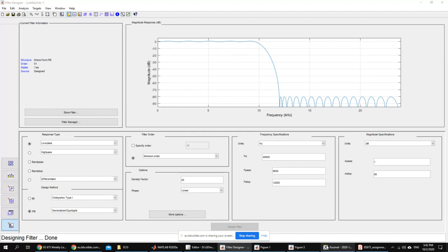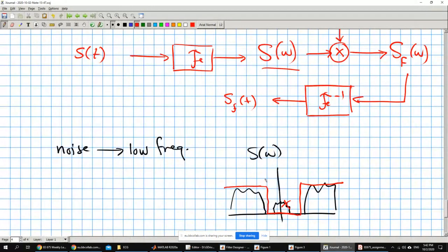So you can have an ideal filter where, for example, this value can be at 1 hertz, it would pass, and 0.999 would not pass. So if it's there or higher, it's okay. Here or lower, it's gone. You can have a transition region that is really very small. All we have to do is get the frequency domain, look at the frequencies that we don't like, and make them 0, and that's it. Go back. This is what we did last time.